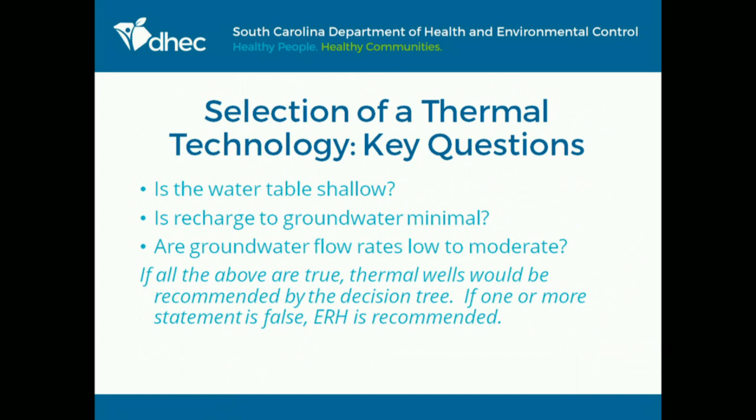And it's really wonderful if you think about drying out clays and heating them up, you can really drive off a lot of contamination out of those clays. But thermal wells are not effective if you have a lot of groundwater coming in that changes the temperature of the subsurface. So you want low recharge in this case.